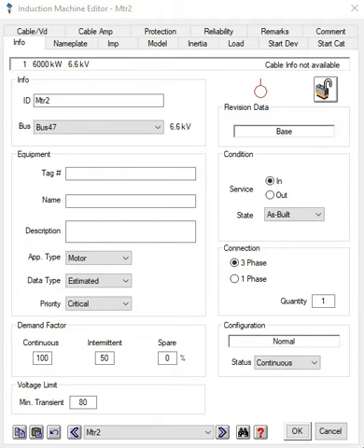So basically motors are generally used in both industrial and domestic applications. Specifically, if I talk about the operation of an induction motor, it runs due to the induced electric current in the rotor circuit by the varying magnetic field in the stator windings. The rotor current produces its own magnetic field, which then interacts with the stator field to produce torque and rotation. And this accelerating torque basically creates the voltage dip.